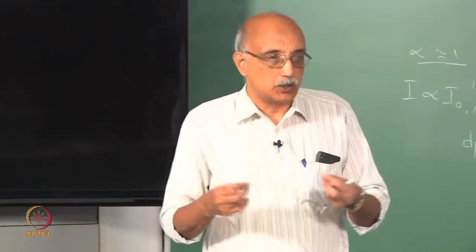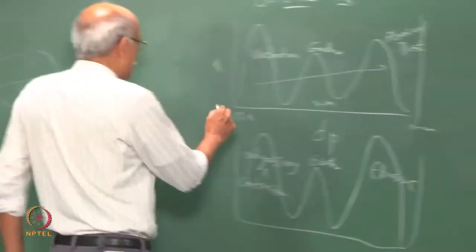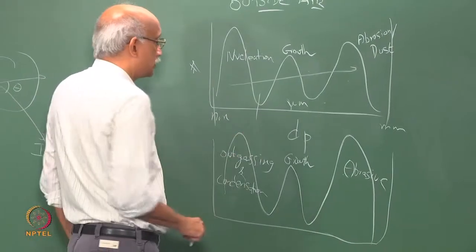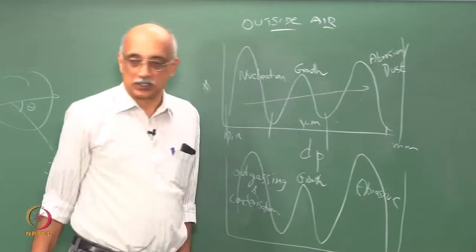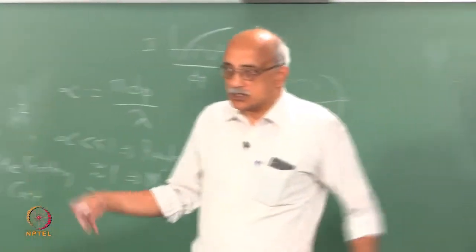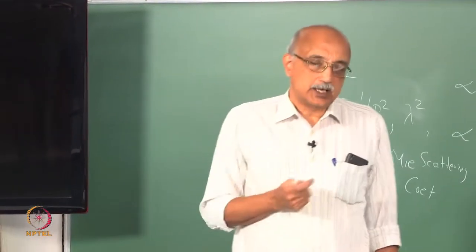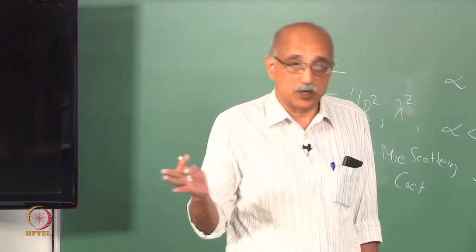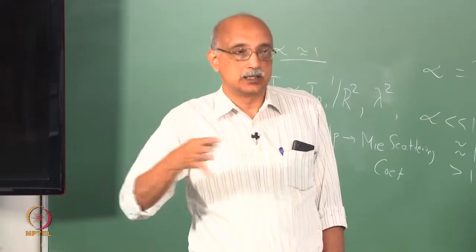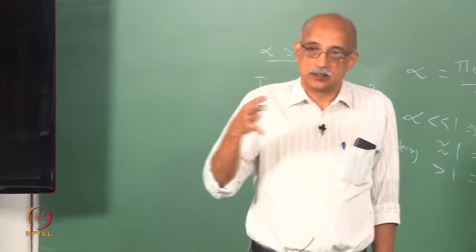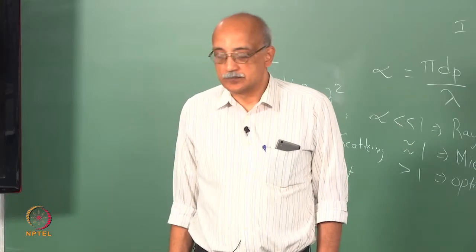So whatever particle counter you use should either be optimized for measuring in a certain size range. For example, you might choose to use one particle counter here, a different particle counter here, and maybe some optical system to measure the larger sizes, and then you put all the data together to get the full description. The difficulty with that is that different methods of particle size measurement are not easily correlatable. So you might see significant discontinuities between these three types of measurement when you actually plot and examine the data.